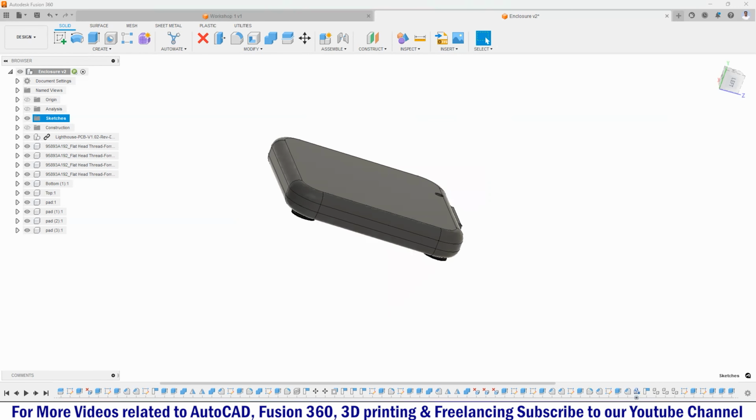Then we got another folder called origin, and inside this origin folder, right now here you can see it's turned off. So if I want to turn it on, I can just click on the eye icon over here, and here you can see it got turned on. Now if I go onto the home position, here you can see we got 3 different axes, default axes, and we got 3 different planes, right? So we got the origin first, that is this point. Then we got the x-axis, that is this axis. Then we got the y-axis, that is the green axis. Then we got the z-axis, that is the vertical blue axis. So x is red, y is green, and z is blue.